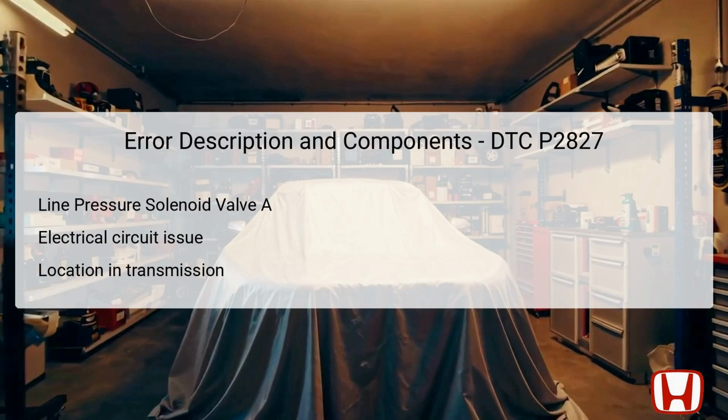DTC P2827 signals a high input from the line pressure solenoid valve A, which is integral for regulating transmission fluid pressure. The solenoid valve's function is to control the line pressure that the transmission relies on to shift gears smoothly. If this valve is not functioning correctly, it can lead to erratic shifting, poor performance, and even potential damage to other transmission components. The valve is typically located inside the transmission assembly, connected to the PCM via wiring harnesses. This connection is essential for the electronic control of the transmission.